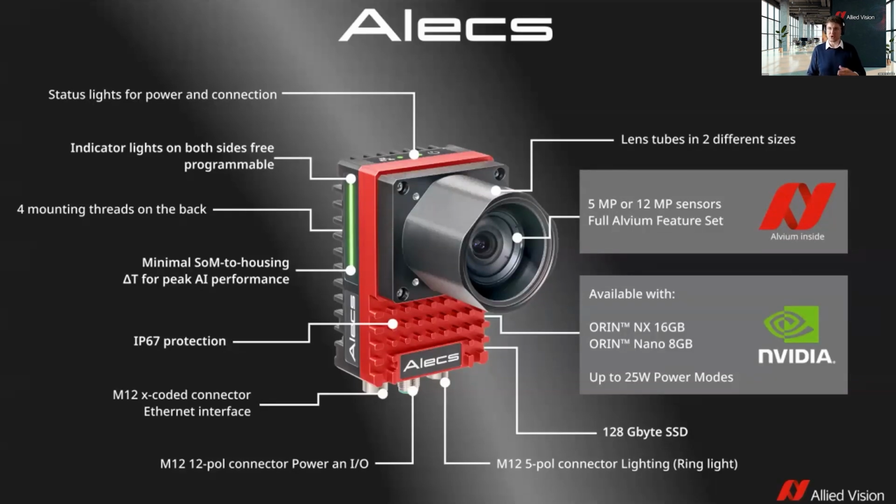And each SOM, not only from NVIDIA, has dedicated chips which you can enable step by step. For this, there are different power modes available. It is necessary to know that because, based on the thermal design, as we heard before, you can expand your tera operations per second. There is a watchdog inside the system which decides if it's too hot and decreases the power frequencies of the dedicated cores. With the Alecs, we have a dedicated thermal design which allows us to use the high power modes of the NVIDIA SOMs inside. But that's everything about the hardware. Details you can check on our webpage.